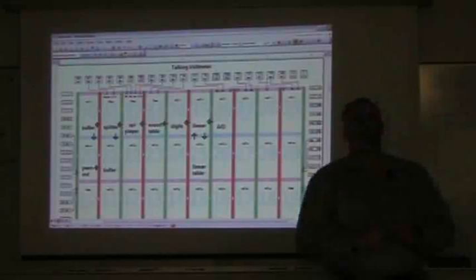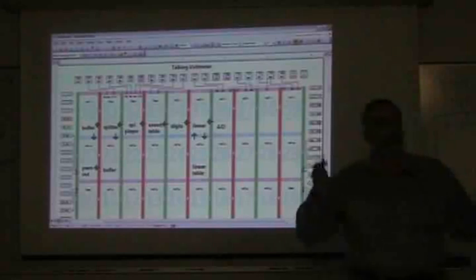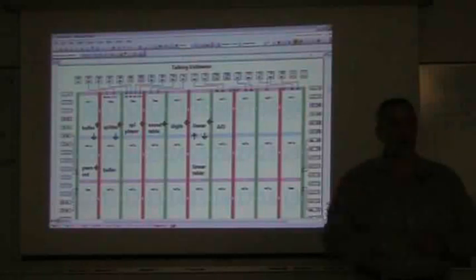It's similar to I2C, but a little less complicated. It's a simple device. I2C has more command variations. And SPI, the important thing about it is that the processor generates the clock, which can be anything from DC up to the maximum speed that the parts run at, which today is about 55 megahertz. So they're very, very simple, very cheap devices, and that's what we're using for our flash interface.